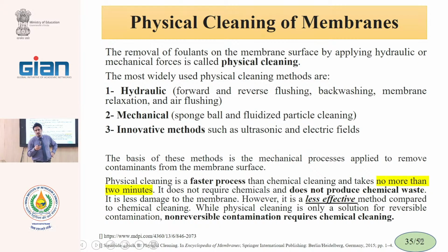But in chemical cleaning, we need time for the reaction between the cleaning agent and the fouling. For example, we want to remove scaling. When we use acid together with EDTA, the acid and EDTA should go and react with calcium carbonate and calcium sulfate for dissolving it. And dissolving needs time. Therefore, we usually use 1 hour. We do not use more than 1 hour because more contact causes damage to the membrane. And rapidly after cleaning, we use water for removing the cleaning agent.